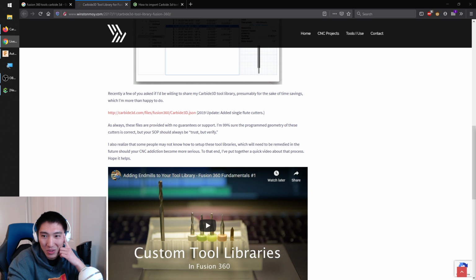Are proximity switches more accurate than mechanical switches? For the kinds of machines that we're using, it really doesn't matter. The resolution of the Shapeoko is theoretically 1/40th of a millimeter. For the Nomad, it's 1/200th. You're talking about a difference of like a thou, if that. Both of them are totally fine, in my opinion. I actually haven't upgraded to inductive or proximity switches at home, so I use them interchangeably. I don't really worry about the precision there.